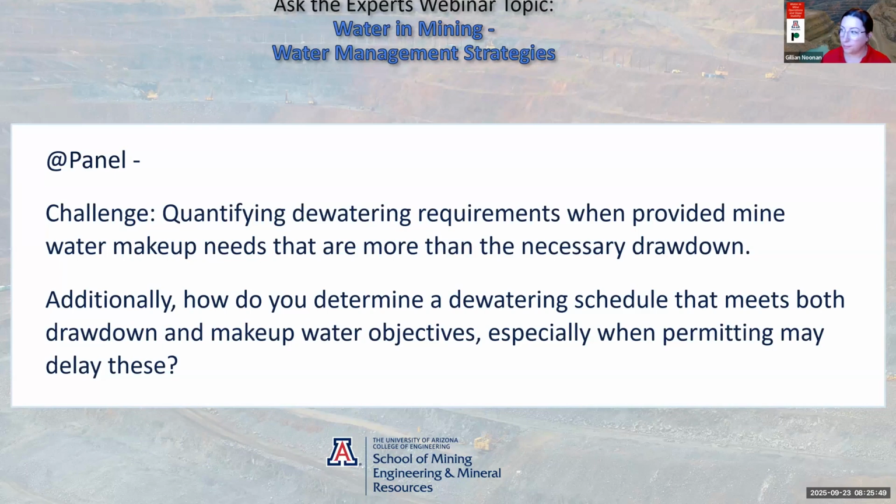Oh yeah, okay. So I was just going to add that a few mines that I'm working on have started to do aquifer storage schemes. If you do have excess water and it's good enough quality, you can store it locally in aquifers. There's a couple of mines I'm working at in desert environments where we're doing that, and there's a well field and wells which both act as injection wells and pumping wells. So that's an option in certain environments. Typically, you need decent quality water for that, but it is an option on the table in drier climates typically.